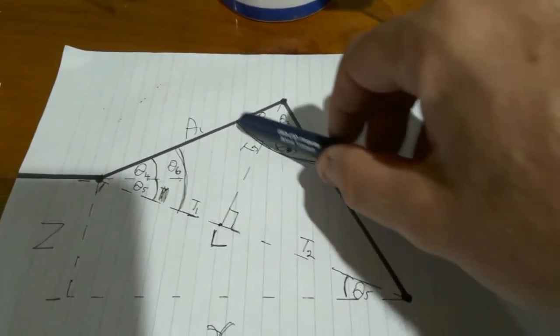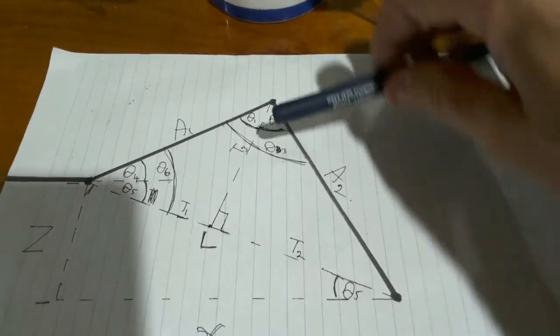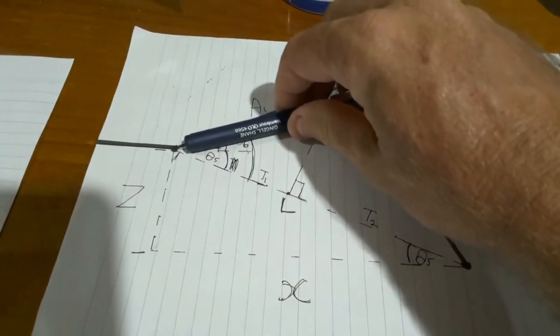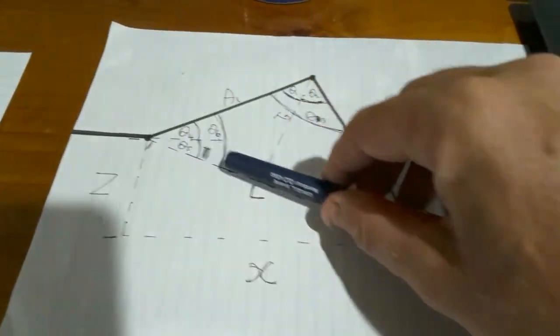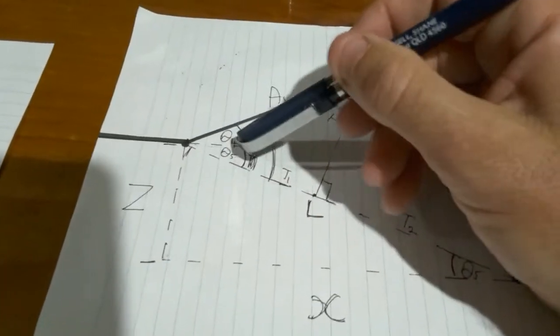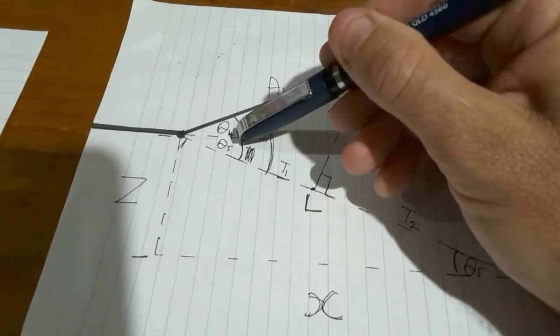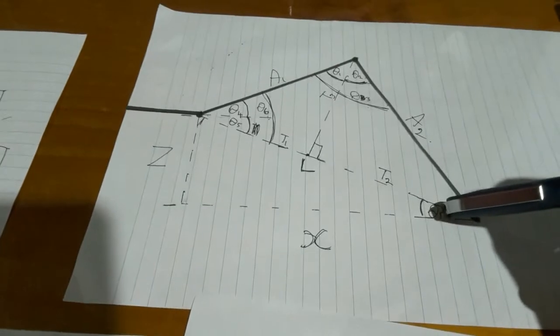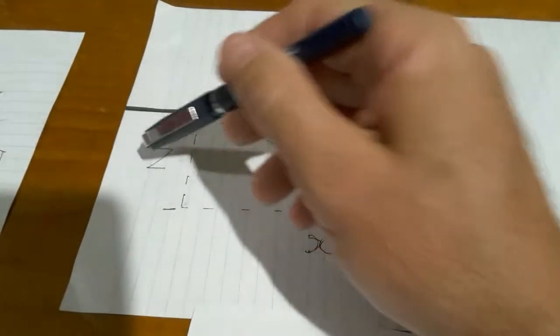So that joint will be at 180 degrees out in a straight line. And then what we want to do is we want to point this angle to point in the same direction as L. So what we will need to do is set this angle here to negative theta 5. And we know that theta 5 is tan z over x.